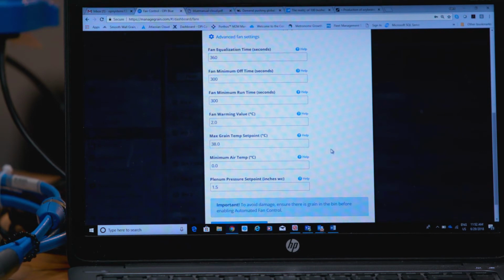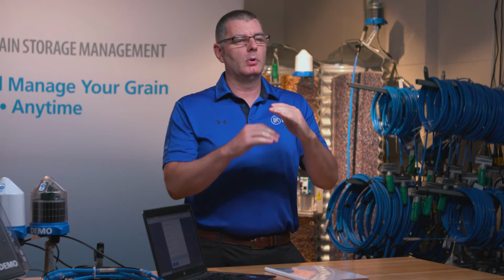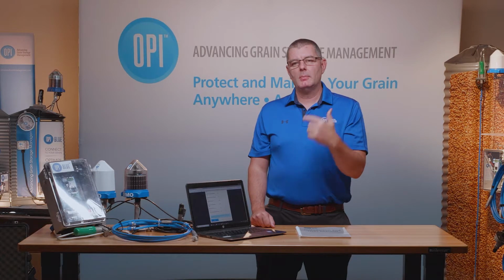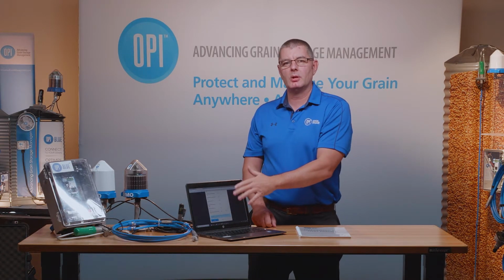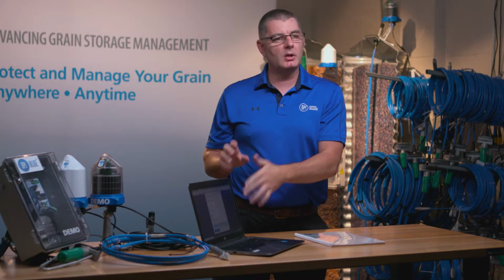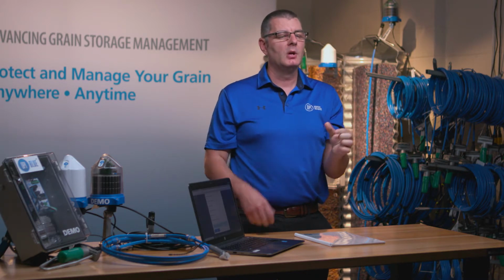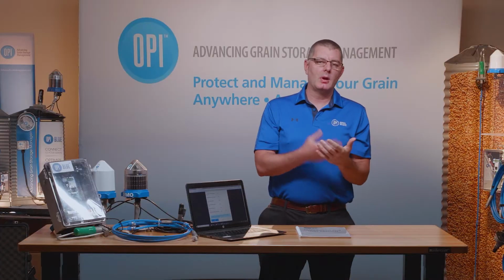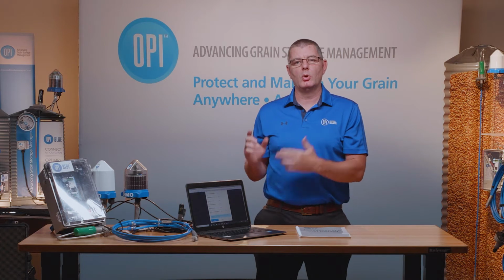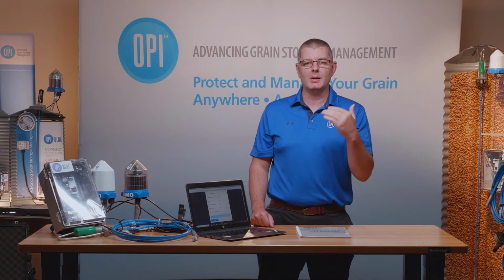We've got the maximum grain temperature set point. So when you're in aeration mode and you're specifically worried about getting a uniform temperature throughout the grain mass in the bin, if the temperature exceeds whatever maximum temperature threshold set point you have here, regardless of whether the conditions are met to run the fan, the system is smart enough to know that you either have a hotspot developing or a hotspot that has developed, and the fans are going to automatically turn on to cool that hotspot or warming grain down.